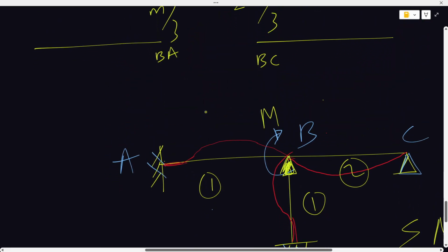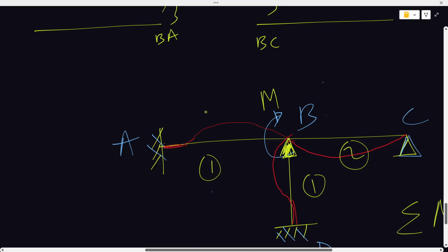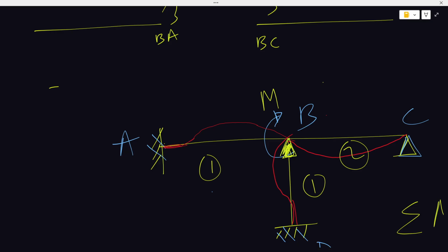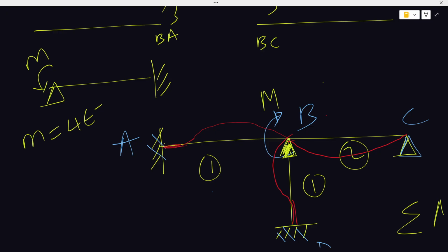So once again, let me come down to explain. Initially, we looked at this beam when we were dealing with the first case. It was a hinge. And we said if we apply a moment here, that moment is equal to 4EI theta over L. But this time, this moment you are seeing here is now here.